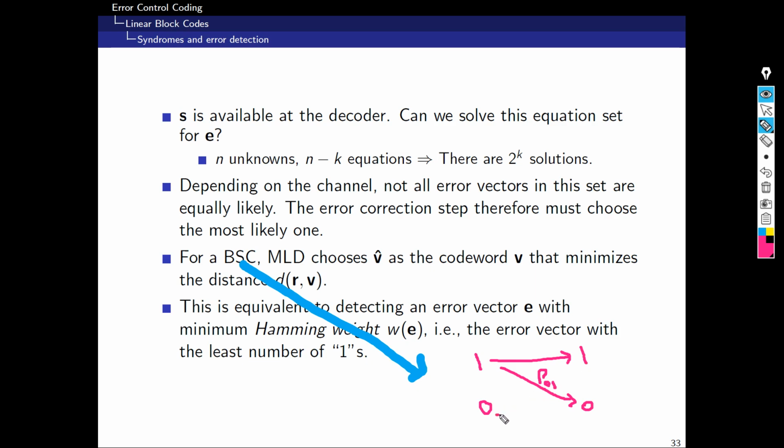And the 0, if you receive it as 0, we call that the reception is correct with a certain probability that we will write its value later on. And if you receive the 0 as 1, we call that you have made an error. And this error, we call it B10. So now, what's the probability of receiving your bit successfully? It's 1 minus B01.